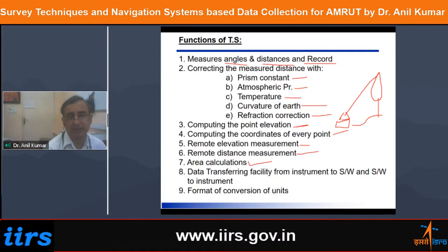Data transferring facility from instrument to software, or to laptop or PC, or from laptop or PC to instrument. You can use just a pen drive. You can copy your data to the pen drive, and through the pen drive you can upload or download the data in different formats like AutoCAD DWG format, or DXF format, or shape formats. Shape can be 2D or 3D. Format conversion: you can convert the data into different formats as well as units. If you have measurements in feet, you can convert that into meters and so forth.